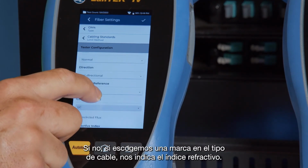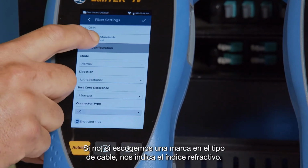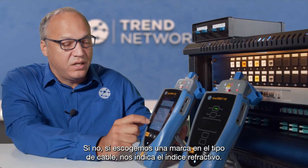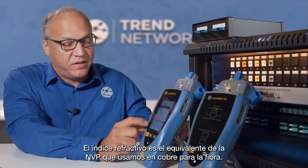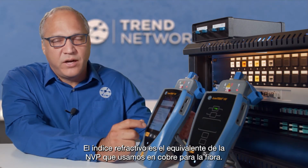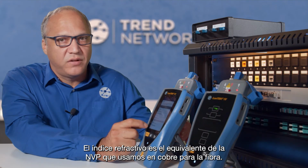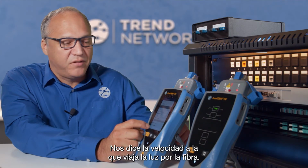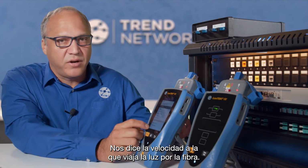Otherwise, we could have chosen from the cable type. If you choose a brand of cable, the refractive index will be set for us. So refractive index is the equivalent of NVP that we use on copper. That's the equivalent on fiber. So it tells you how fast light is traveling through the fiber itself.